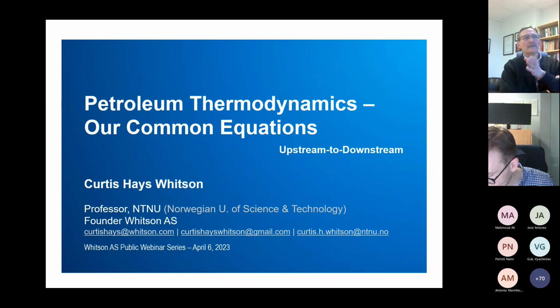Water, H2O, has been shown you can actually model with the cubic equation of state, water and non-aqueous phases, gas and oil, very accurately on the component partitioning, mutual solubilities. In a few different ways, you can do that quite accurately, I'd say, for the most part. What hasn't really been done properly for the water, I would say, is to get the compressibility of the water accurate. You can get solubilities, but the water compressibility predicted by the cubic equation of state is off anywhere from 20 to 40, 50%. So something needs to be done there. We're working on some things, but that's not really been solved yet.